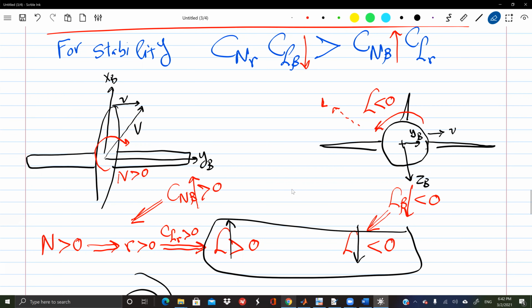Yes, Abdullah. So does the large yaw induce the rolling, or is it the other way around? The yaw is what induces the large moment. Yes, exactly. Simply put, without all my complications, at the beginning the airplane will roll to the left, here by roll stiffness, but yaw to the right. But the issue is that the yaw is strong, and the yaw is always associated with the roll moment. So the roll moment coming from the yaw is too strong and will overcome this thing, simply.